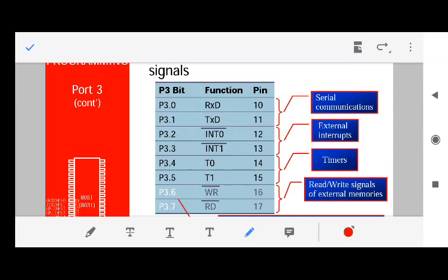In a similar way the 8051 works. When 8051 is executing a program, and if any interrupt comes, for example there is a hardware failure, a power failure, or you press some keys on the keyboard, that is an interrupt for 8051. Fine. So to get the interrupt from the output units or from the other units to the 8051, you have two inputs, that is interrupt 0 and interrupt 1. So there are two pins from which interrupt can go into the 8051. We'll cover what interrupts are in unit 3.